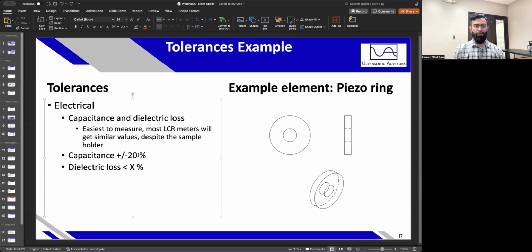So capacitance can vary a significant amount. Either you could put a tolerance of plus or minus 20% from a few small batches that you got for your prototypes, or you can ask the manufacturer what they put. If they recommend a tolerance, like if they're fine with a tolerance closer, then I would always obviously assume that that would be the best option.